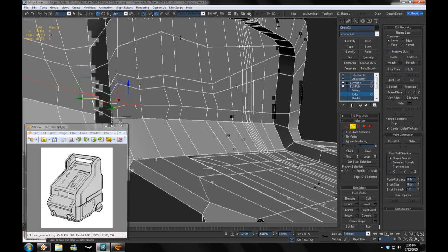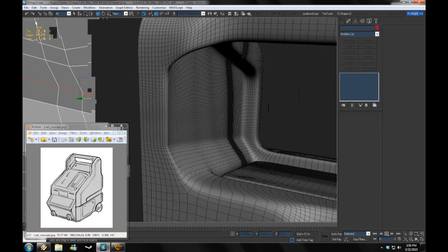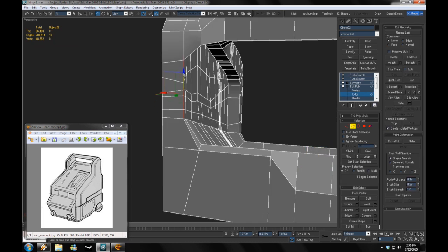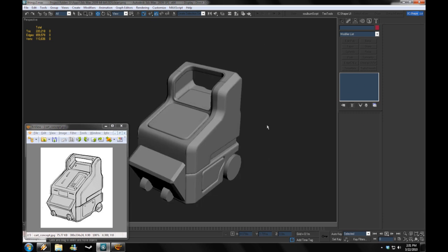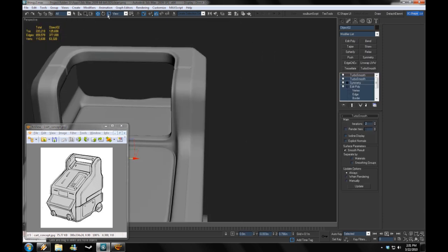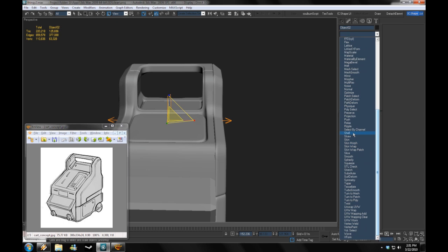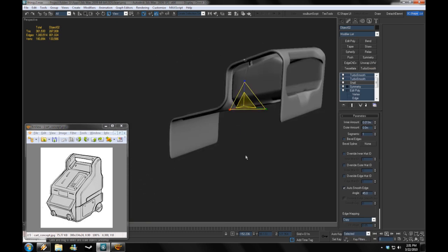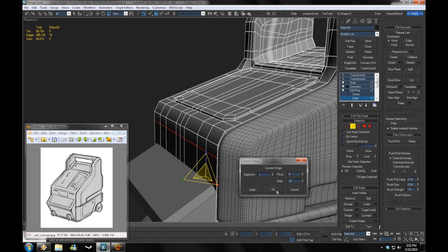And I'm adding this edge loop in. The video just went crazy, but you can see that the hard edges are starting to get defined towards this angle. And we've got most of the cart subdivided. And also I want that nice little lip, so I'm going to add a shell modifier and tweak the extrude amounts. And you can see that now we have that nice bevel on the edge of our parts.